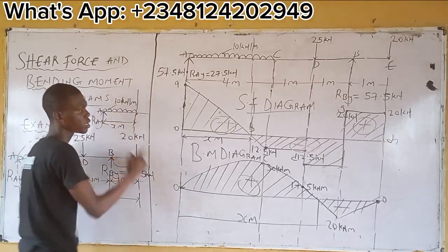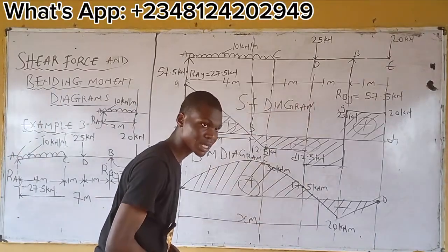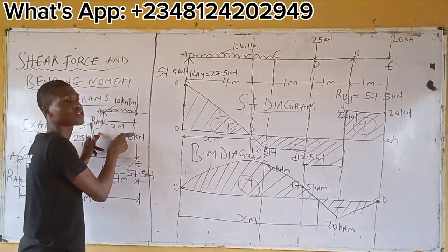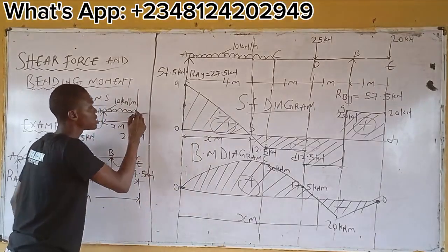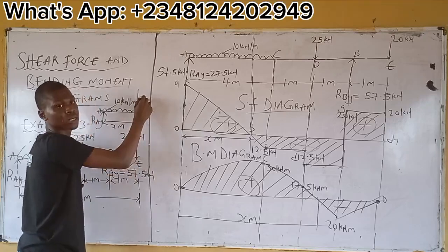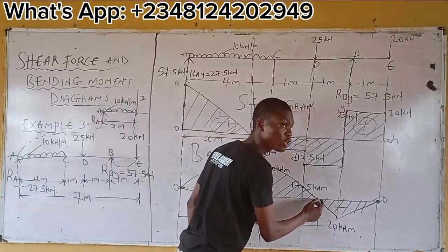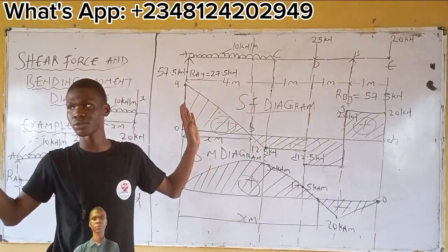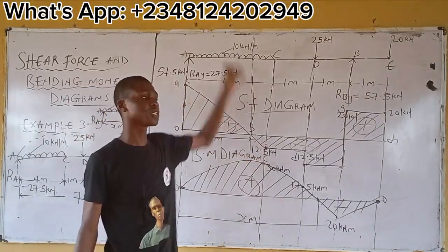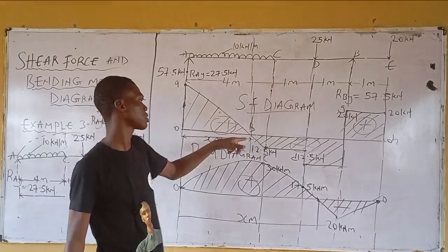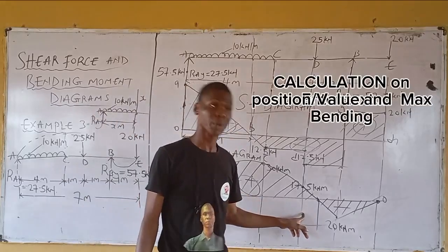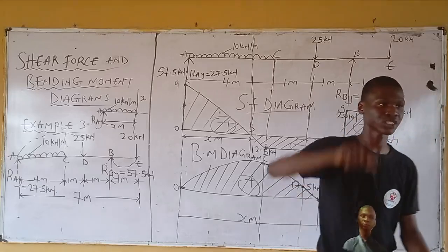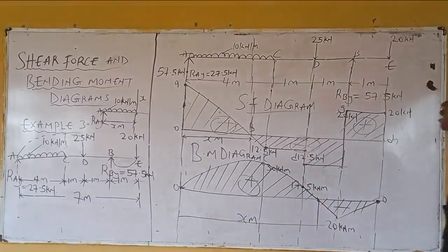The same way you section this also, you have another type of beam, right? Now, where do you section this beam from? Is it from shear force or from bending moment? Just because you've sectioned from the shear force diagram, take shear force about this point, you get the value of x. Just because you've sectioned from the bending moment diagram, take bending moment about this point, you get the value of x. Do you understand at all? So what we are saying is that once you've sectioned, take shear force about the point you've sectioned, get the value of x. For this, take bending moment about the point you've sectioned, you get the location where point of contraflexion has occurred. So this is shear force and bending moment diagram.